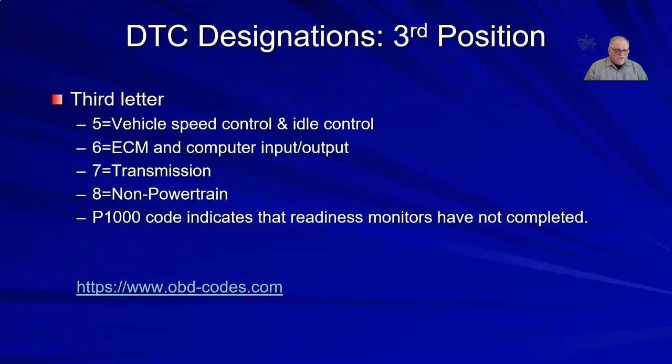The P1000 code, I've only seen that on Ford. What that meant was readiness monitors are not complete. If you clear codes on there, you'll have a P1000 until all the readiness monitors are complete, then the P1000 will go away. So that actually was not a DTC.